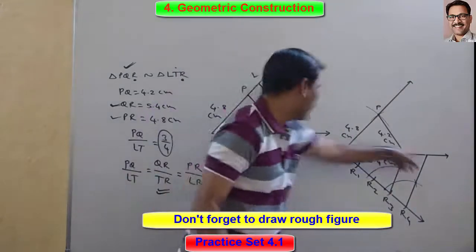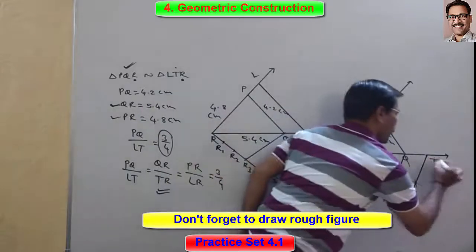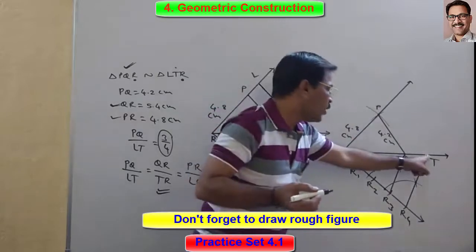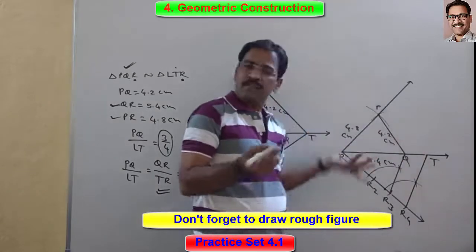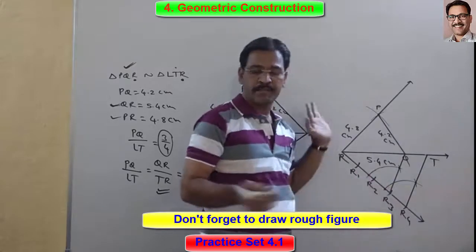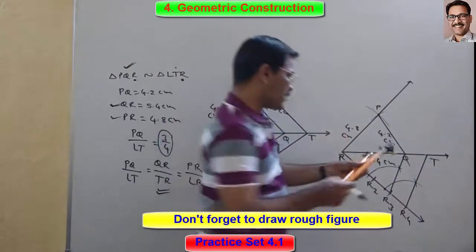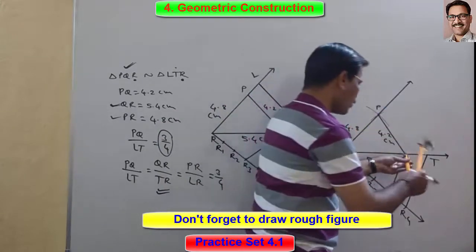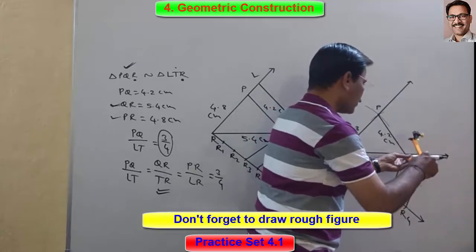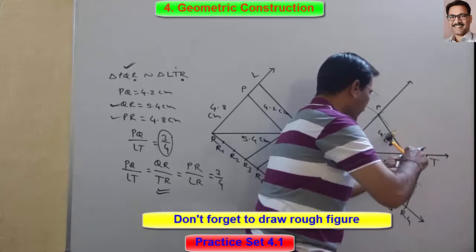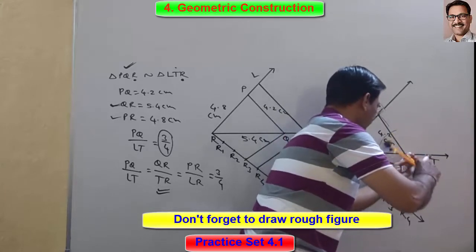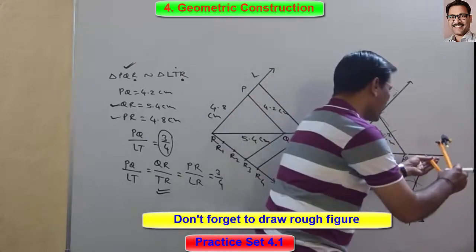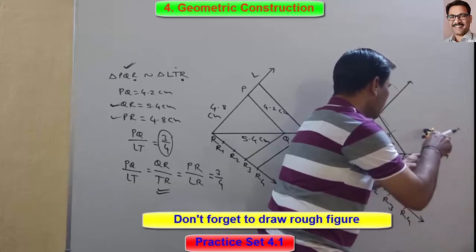Now that is the point which is nothing but point P. Okay. Now just 1.2 remains here. Here it is L. And from point P, we have to draw one parallel to this PQ. Just repeat the same procedure that you made here. Again, I will take some distance in the compass, that should be from Q. Now from point Q, in this way, like this, we have to draw one arc here. Okay. Now by the same distance, I put on P and again try to draw one arc here. See.